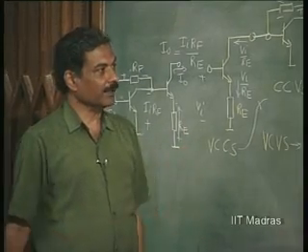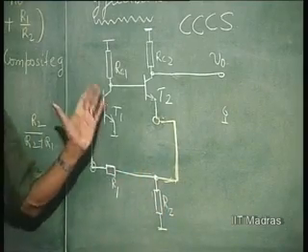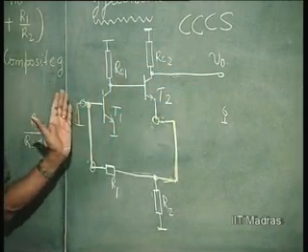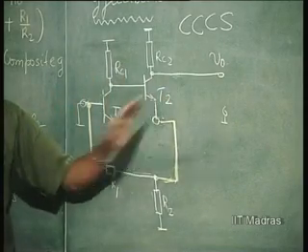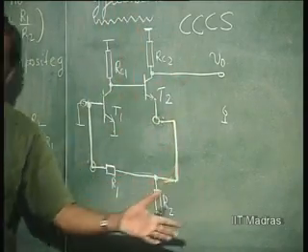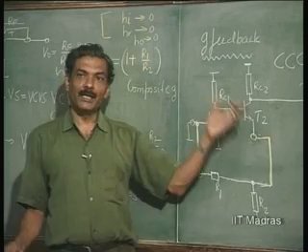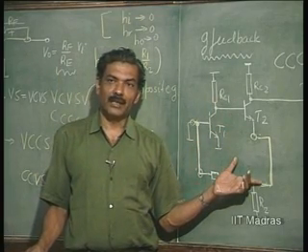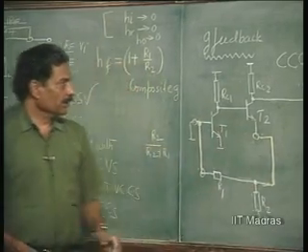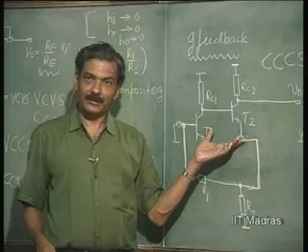So, it is not always advantageous to simply cascade amplifiers and then give overall negative feedback. As you cascade amplifiers, the individual time constants will cause a delay in the whole structure, and the phase shift will change in such a manner that what you consider negative feedback at a certain frequency will turn itself into positive feedback, and that is a danger. The positive feedback with loop gain greater than 1 will cause what is called instability in amplifiers or oscillations. Okay. So, this kind of configuration for more than two pairs is definitely dangerous, right.